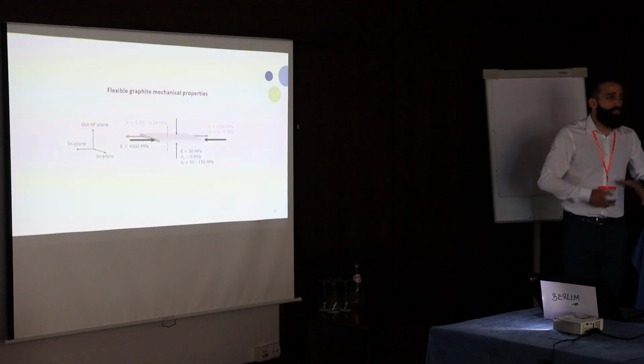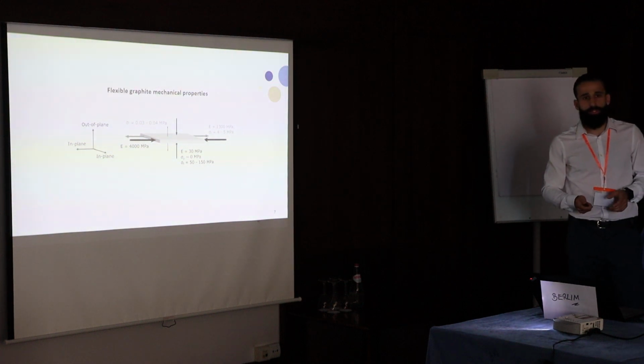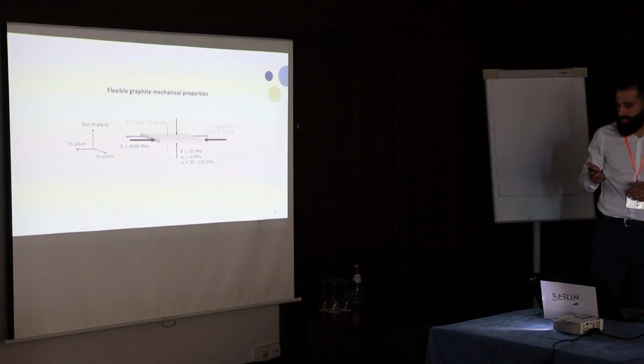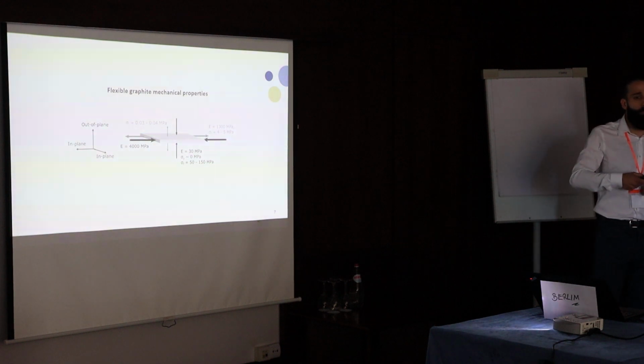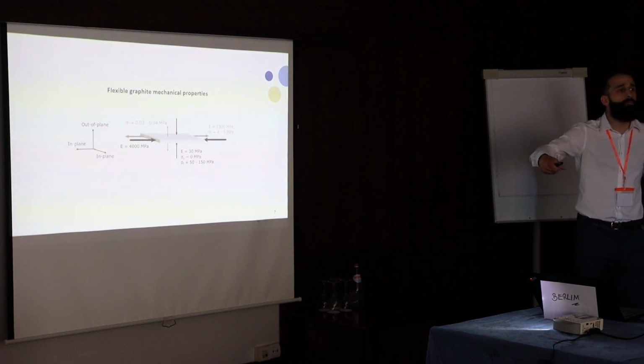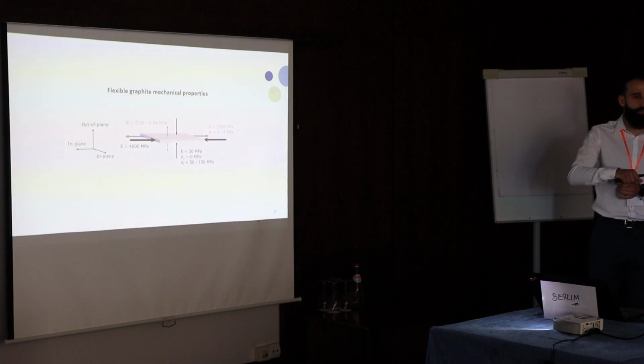Its mechanical properties are not really well known, also because the applications are not. Our application is quite unique, I would say. But what we know is that it's orthotropic, so if we pull it or compress it in the in-plane direction, the strength is different, and also if we pull it or compress it in the out-of-plane direction, the strengths are different.